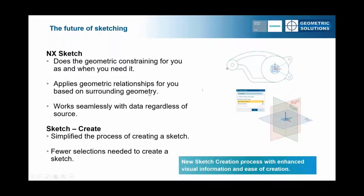Because what the new Sketcher does is it does the constraining for you as you need it, when you need it. Now, we might say, wait a minute, the previous versions of NX would create constraints as you would sketch. And to a point, that's true. You could put in a parallel or perpendicular or horizontal, vertical, and it would know what you were doing. But it was very limited. With the new sketch solver, we're able to look at all the geometry around what we're drawing, and it'll apply some of those relationships. What's nice is it works seamlessly with the data regardless of the source.